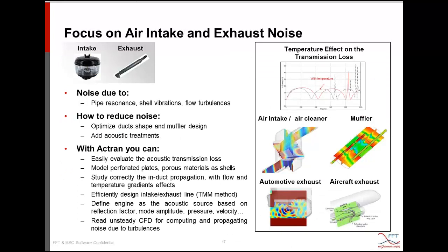So now let's talk about the noise coming from air intake and exhaust. It can be due to pipe resonance, shell vibrations, or flow turbulences. This noise can be reduced by optimizing the duct shape, the muffler design, and by adding acoustic treatments.